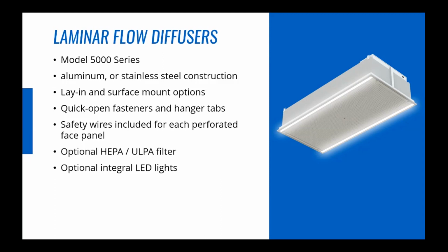And in the illustration, you can see the LED light strips. These are becoming more prevalent as OR room sizes increase. With larger rooms, you require more air changes. So 20 air changes in a larger room is going to require more air. So you begin to encounter issues where you may not have enough real estate in the ceiling to house all your light fixtures and air distribution and meet the 20 air changes required by ASHRAE 170. So if you integrate some of those light fixtures directly into the diffusers, it should be easier to adhere to the ASHRAE standards and provide enough air changes per hour.